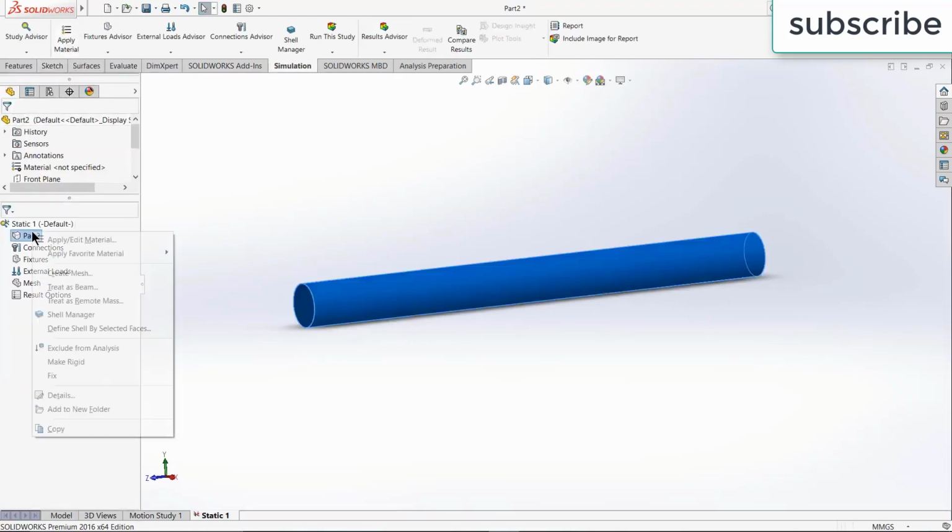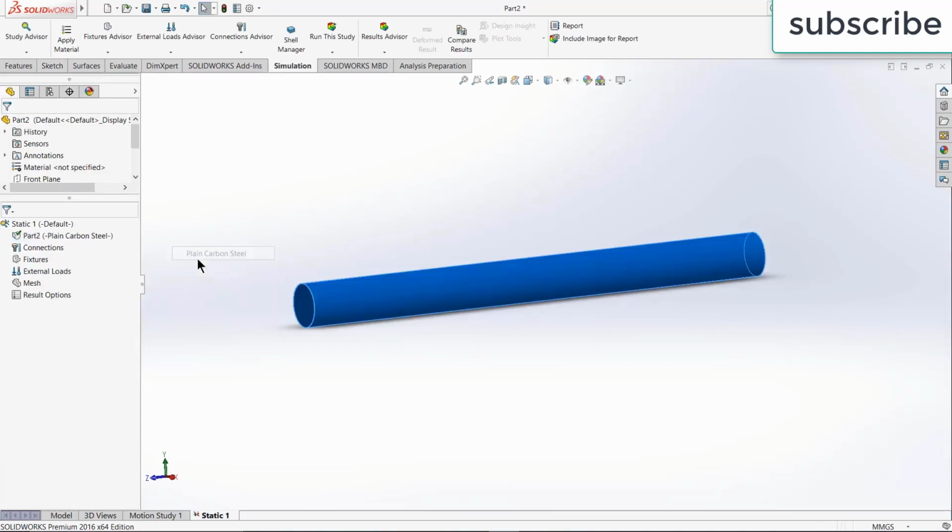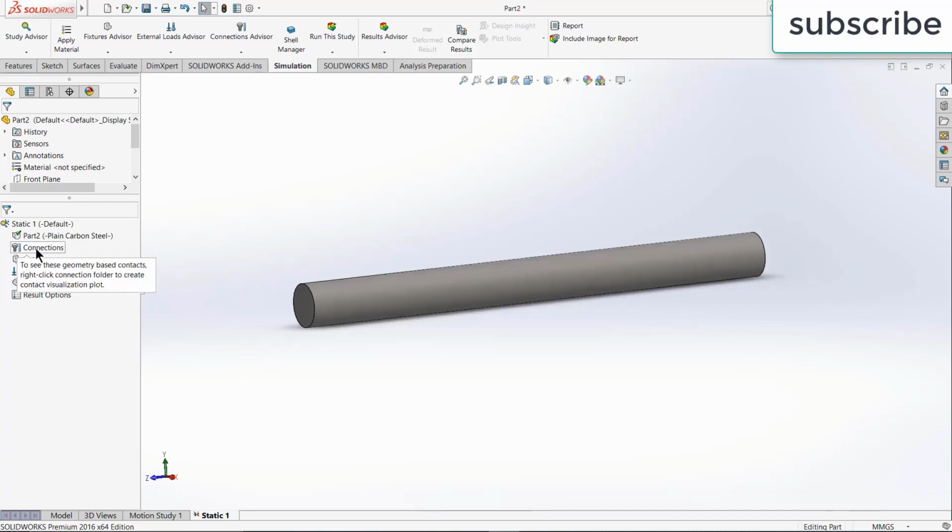Now after that, go to simulations, click on new study, click on static, click OK. Now apply the material as per your requirement. So I am applying plain carbon steel, but you can choose any other material. Next thing is fixtures. Here you see an option called connections. Connection is basically used when you have more than one or two parts, or features that are not merged with each other.